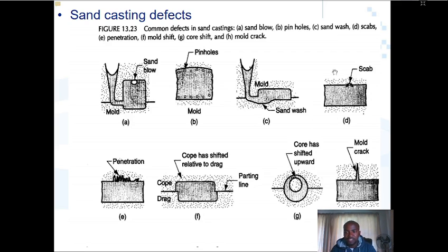D, over there we have scabs. Also you have sand that collapsed, and then on top it was covered by molten metal. Penetrations, collapsed sand, and then you have penetrations of that. All these defects you can start fixing with some method. I can just think of grinding this off to have your part back straight.